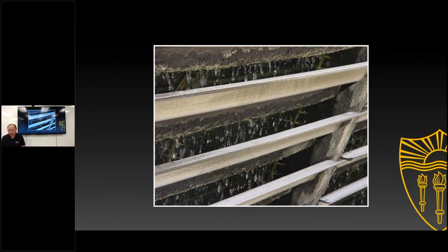Most of the ones you'll see out there will have vents on the cooling tower as part of the cooling process. So you have some of these that have a natural draft, where as the heated water goes down the vents, just the air that's flowing through the vents will cool that water enough to the point where it then goes down into the basin and is stored in the basin, and then from there it's pumped back into the building for the equipment and so forth. So it just goes through that recirculating process of taking the cool water, running it in, that cool water gets heated, sending it back, cooling it again, and so forth.